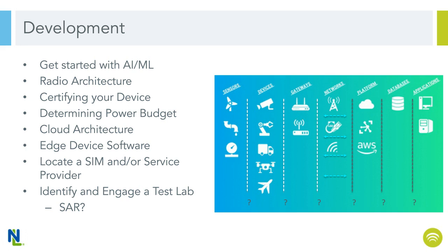So, for example, T-Mobile has a lot of 600 megahertz service across the country. If you're using an edge device that's going to be buried deep in a building, that 600 megahertz is going to propagate easily outside the building, much easier than like a 2.1 gigahertz signal from a different carrier. And so understanding the capabilities and the services that your different providers will give you is really important there.